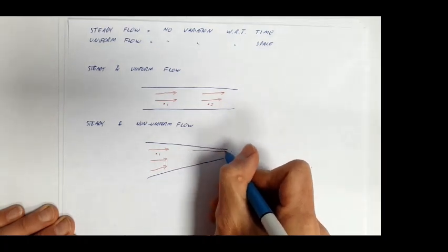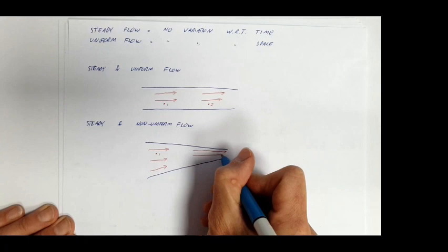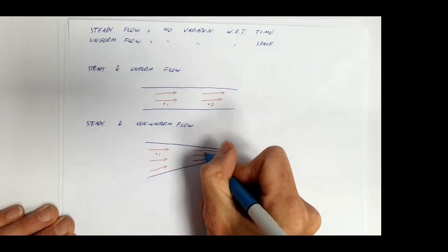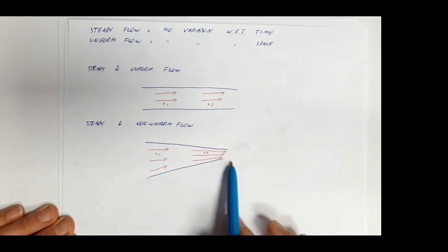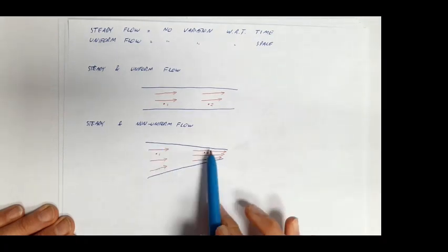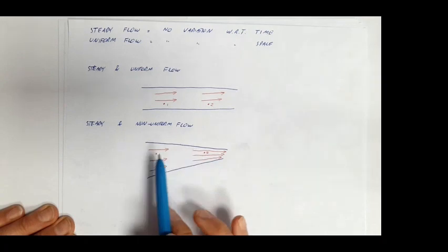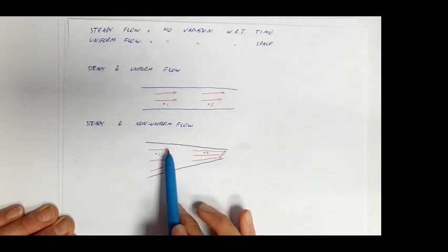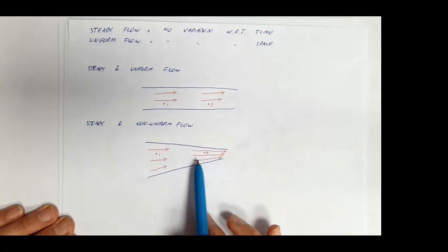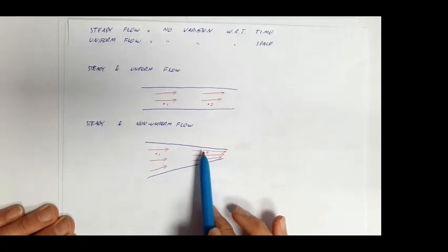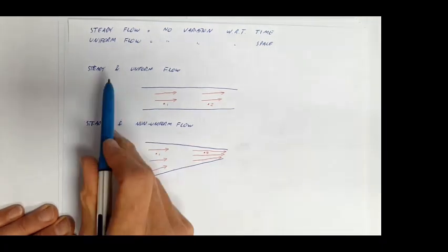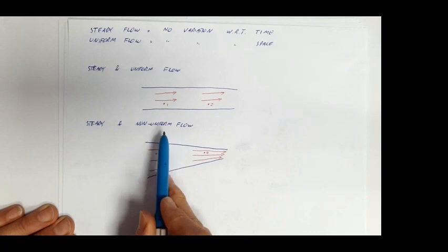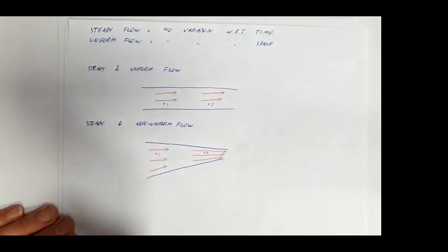Down here, due to conservation of mass, the same amount of fluid passed in the same amount of time is going to have to increase in speed. Let's call that position 2. It's steady, so at time 0 or at time 1, it looks exactly the same. It's not changing with respect to time. However, it is changing with respect to space. The velocity at 1 is clearly less than the velocity at 2. So u is a function of space.